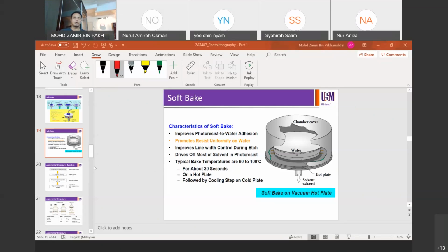So now after this process, your coating is done. The resist is already baked, so then it's already cooled down. Now it's ready for the exposure process. So remember CED. Now the C is done, so now we're going to look into E, then D.